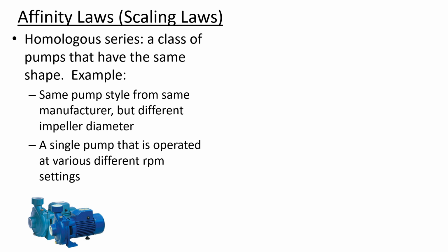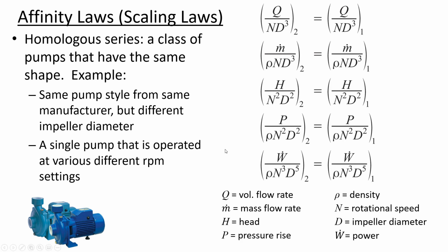The manufacturer maybe has only characterized it at a certain rotational speed. So these scaling laws that are shown here on the screen are a way to extrapolate a known pump into different circumstances. And you can see what each of these variable definitions means.